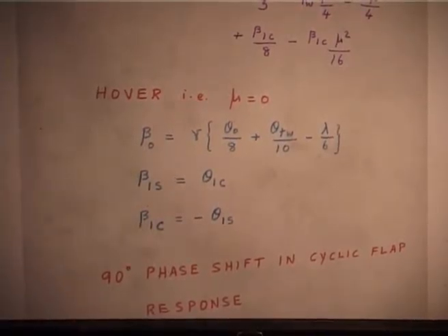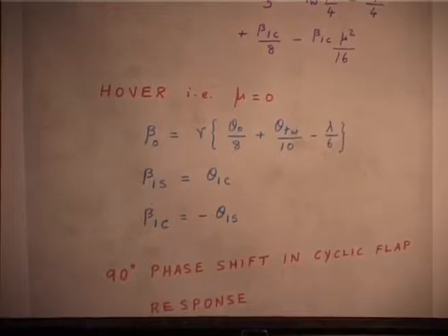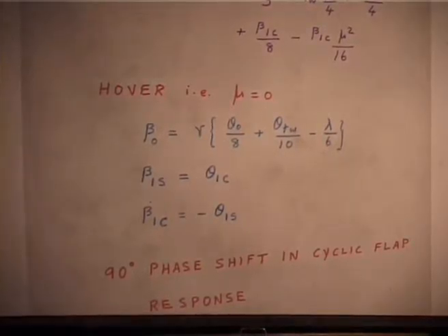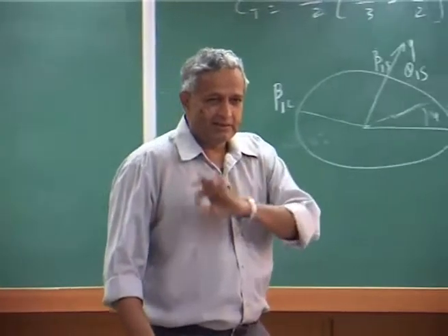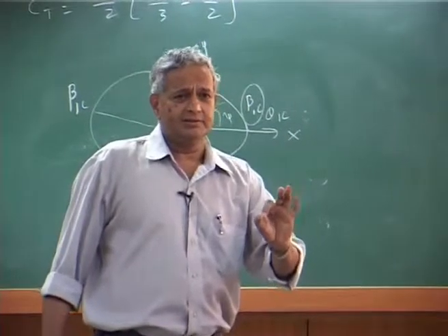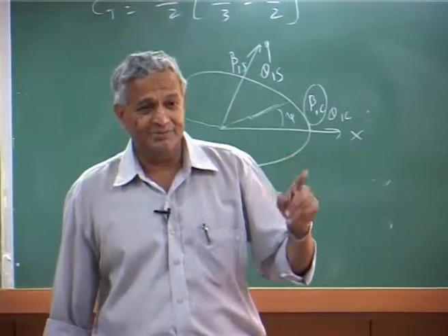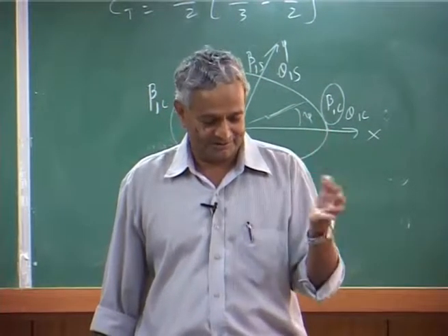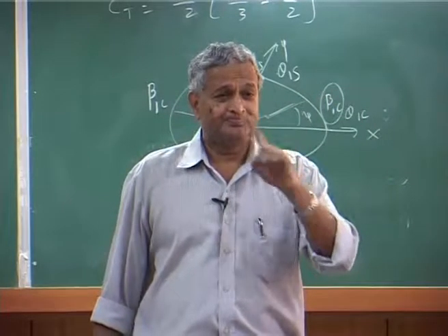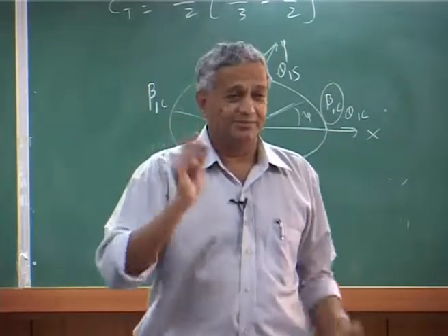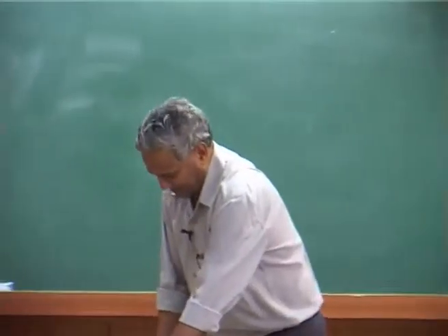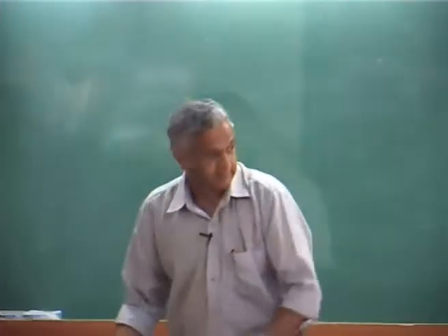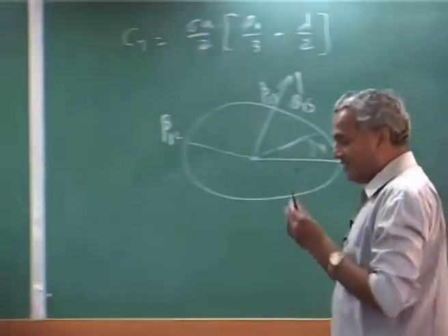Okay. It is a little interesting geometrical interpretation, I thought I will just show you. That is all this for only centrally hinged, because when you say centrally hinged, immediately you must know flap frequency is 1 per rev. That means, flap natural frequency is just rotor RPM itself, nothing else.